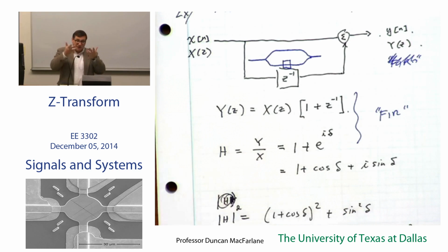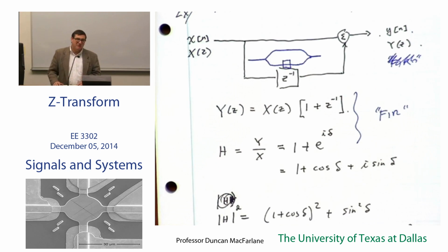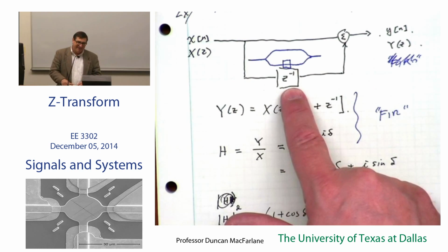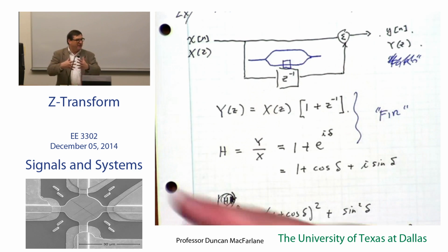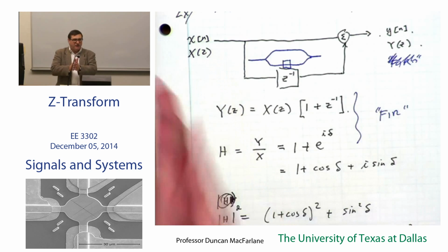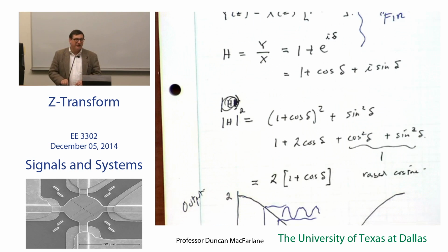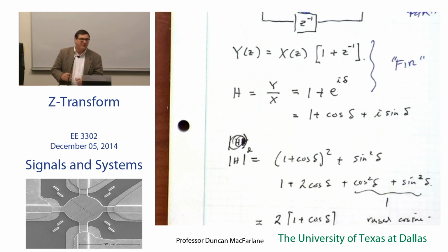Our density goes up. If our density goes up, then the material response goes up, the index of refraction goes up, and the light takes a slower time to go through that branch. If it takes a slower time to go through that branch, it's delayed. Okay? So when these two waves come back together, they come back either in phase or out of phase. And that's the in-phase response and the out-of-phase response, depending on how much of a voltage you put onto this lithium niobate crystal.